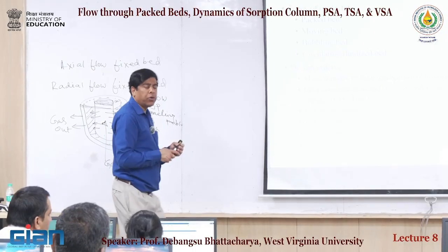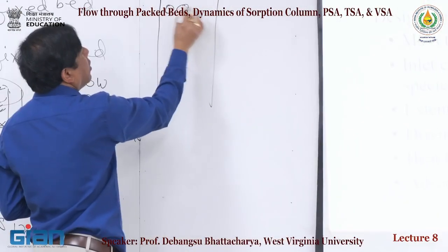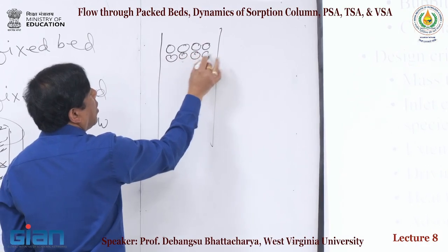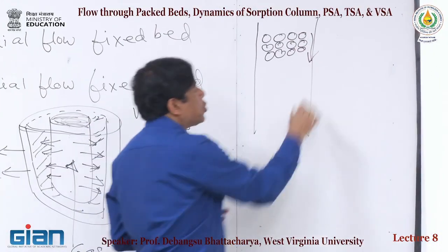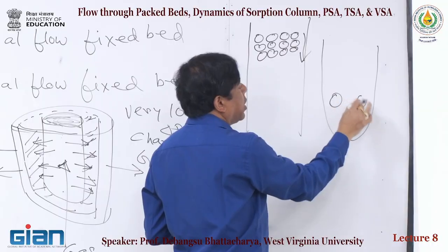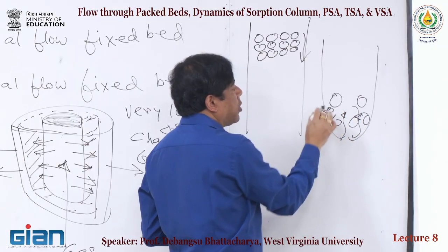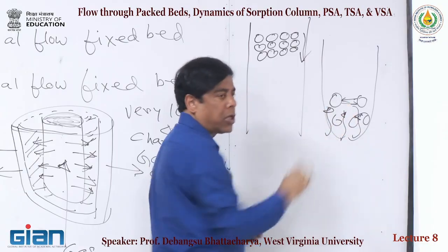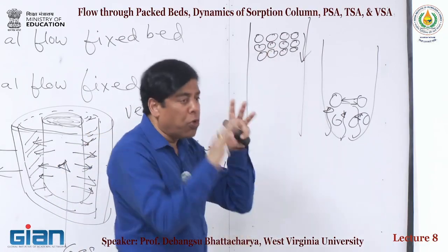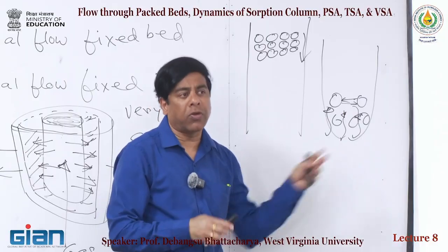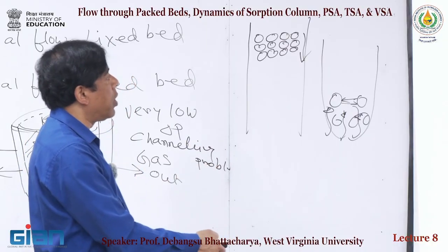If you look into the hydrodynamics of the moving bed, this actually goes like this. This whole thing actually moves, as opposed to a bubbling fluidized bed, where the particles are much more separated. The gas is there, and because the gas is there, the particles go and hit each other. They collide with each other, so the gas gets that and throws it there. But this is actually a more compact bed and flows through the system. So that's how resistance is much less. Okay, unless there are any other questions, we'll move on.